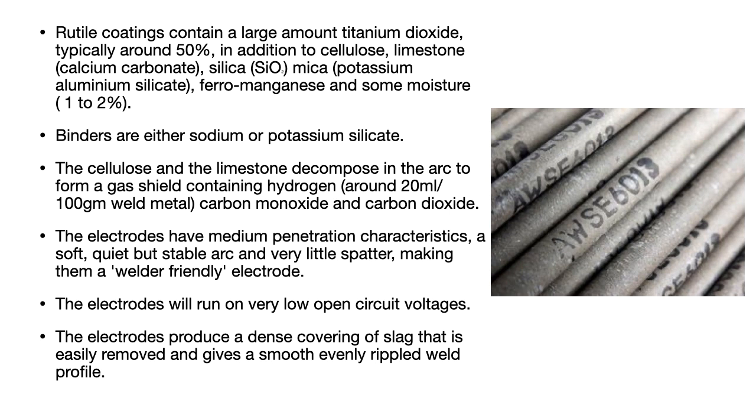The main reason is to make it safe for humans to weld, because if the voltage is above 90 volts or in the range of 100 volts, then we will get an electric shock. But if the voltage is maintained low, then it is much safer for us to perform welding. So this was just additional information which I thought of when I discussed open circuit voltage.